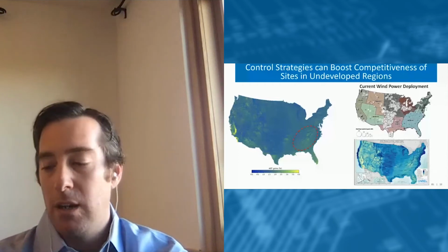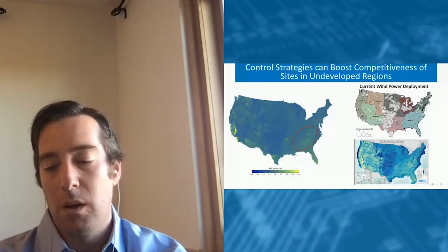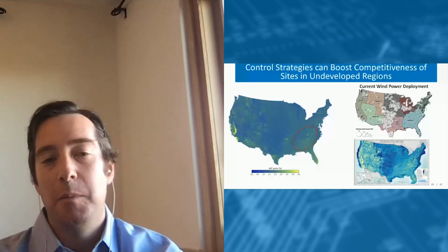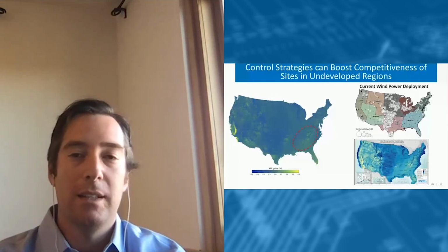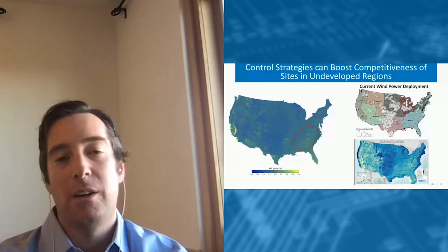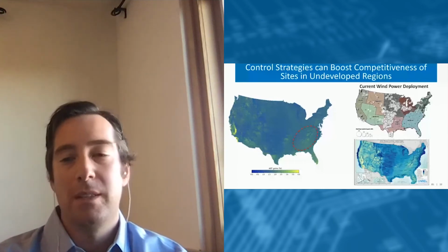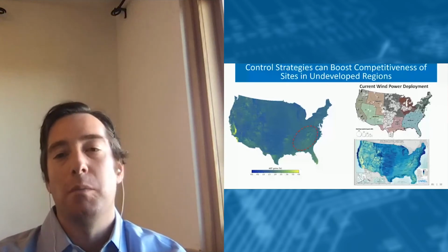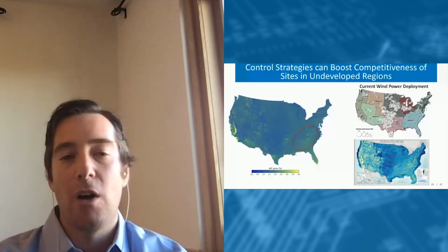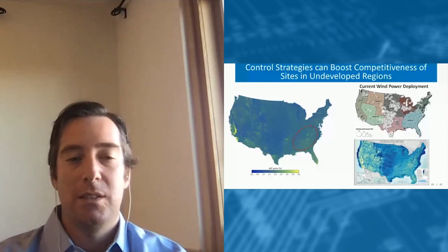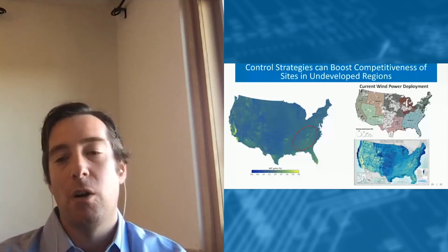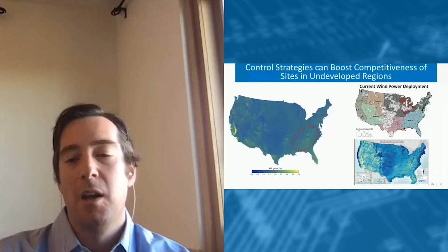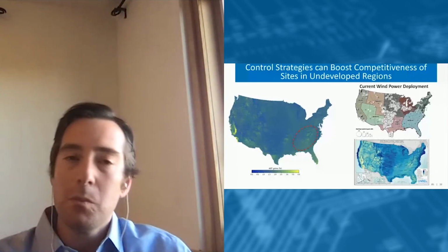For those of you that are less familiar with the wind power domain specifically, AEP gains, and AEP again is annual energy production, of 4% are actually quite significant. This can make or break the profitability and the economics of a wind plant. So depending on other factors, improvements of 2 to 4% are quite significant. They're also in line with what we might expect based on the literature.